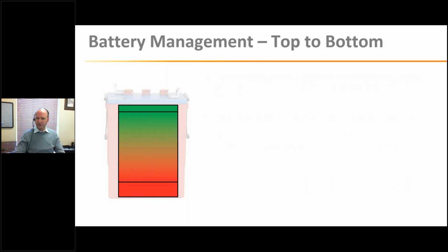Okay, so you can see here, if we look at a really basic graphic to give an indication of where the capacity is coming from in the battery, you can see the absorption stage. That's where we do our magic with PWM or MPPT, our 4-stage battery charging algorithm, and all the settings and technology we've put in place. That's where you take good care of the battery and you give it a nice, graceful top off to make sure that it's healthy and not going to become sulfated.